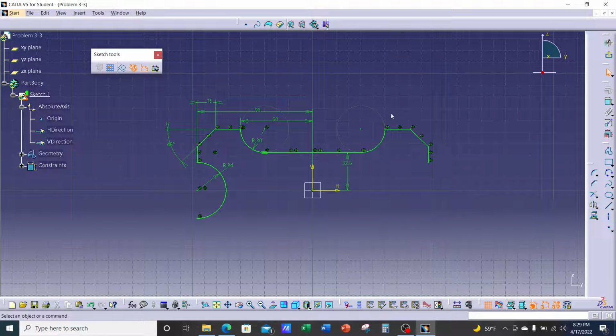So we're actually mirroring to the right. We could have picked the horizontal and mirror downwards. We're going to do that next. All right, so now actually I should have mirrored the arc, which is okay. I was actually going to mirror downward and I got mixed up, picked the wrong axis. That's okay. We had to go in this direction anyway, but I forgot the arc. Let's just do the arc now. Mirror it. Pick the vertical. And there it is. All right.